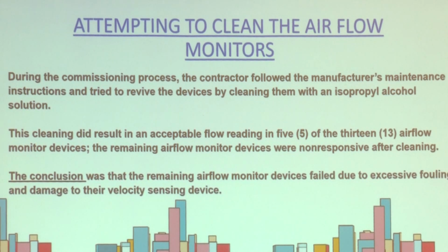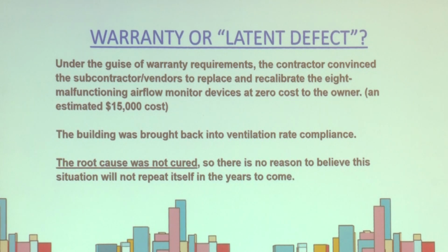So we did attempt to clean the airflow monitors, but it really didn't work. A few of them did work, but for the most part, they didn't. And then over time, they all fouled out and we were in trouble. So what happened was on this job, we had a good relationship with the contractor. So the contractor was able to convince everybody involved that they should go ahead and reinstall the airflow monitors correctly, and that it probably would have cost us $15,000 to do that. But because the contractor was friendly to the owner, they ended up doing that.